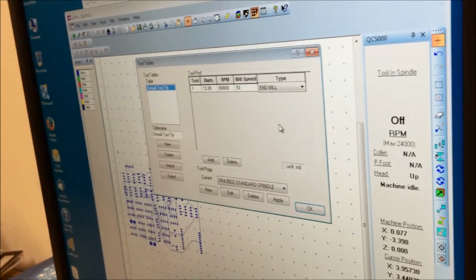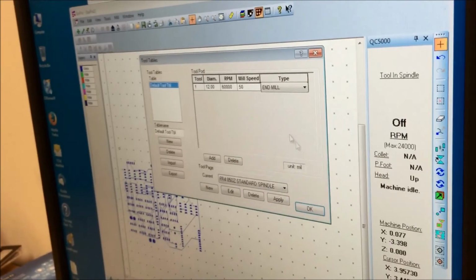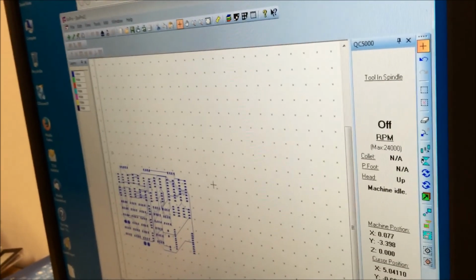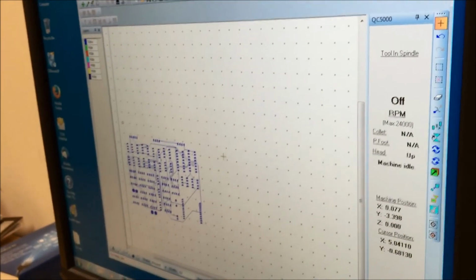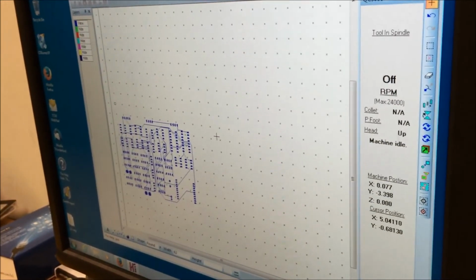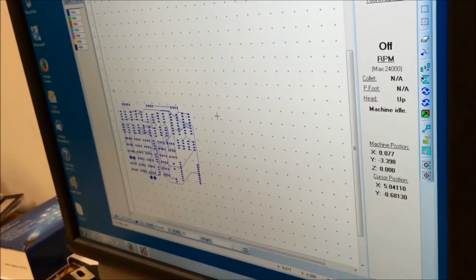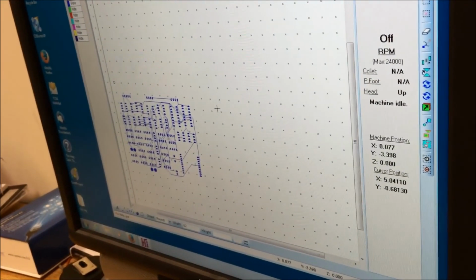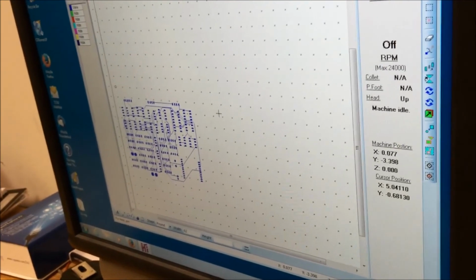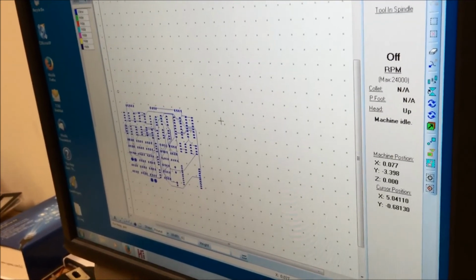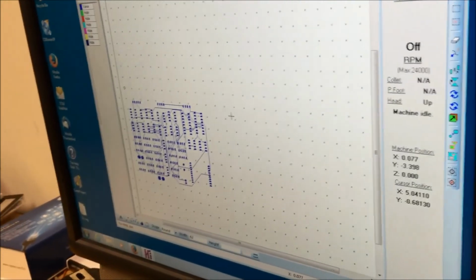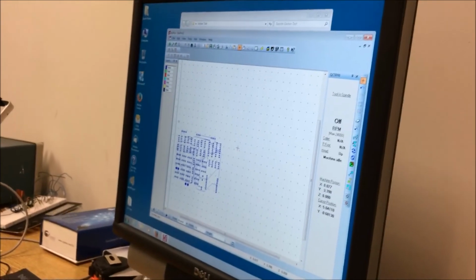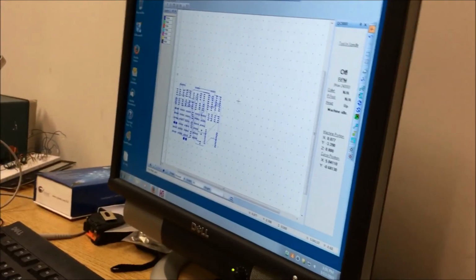But I kept it kind of high level with this thing. So if, instead of giving it a 12 mil tool, you gave it a 50 mil tool or something like that, what would it tell you if you try to run it? I believe if you run it without doing a tolerance check, it would just overrun itself, meaning it'll just create a bad cut. I believe so. Again, I wouldn't say that with 100% confidence, but that would be my expectation. Okay, got it. That's something that I think does come out of the Eagle files too, so it's kind of a double check that's done.